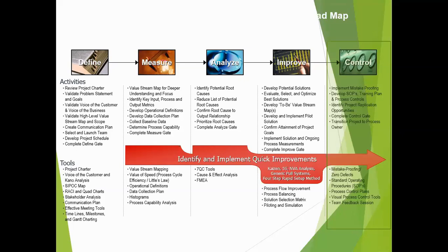We have two types of data, right? Continuous and... no, I'm asking about two types of variation. Oh, abnormal or normal? No, two kinds of variation which contribute to the total variation. So one is process variation, the other one is measurement system variation, right? Mm-hmm. These two put together, you get the total variation.